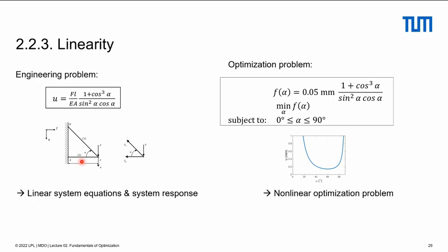It's a linear equation. We combine that with linear kinematics. Linear kinematics means, in that case, when I change my extension of rod 2 by 30%, there will be a change of U by 30%. So linear kinematics and linear material equations all lead to the linear response of U as a function of F. If I double my F, I will double my U.